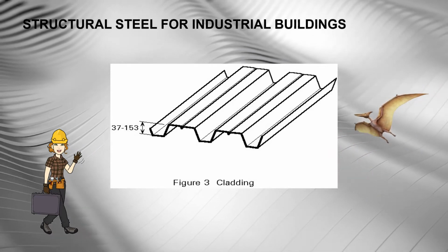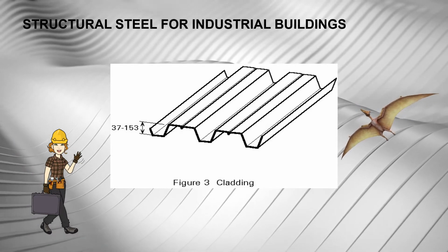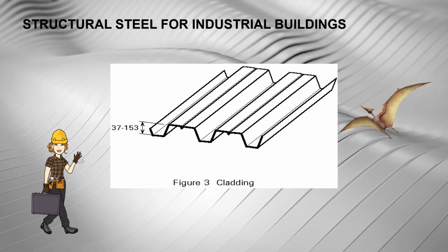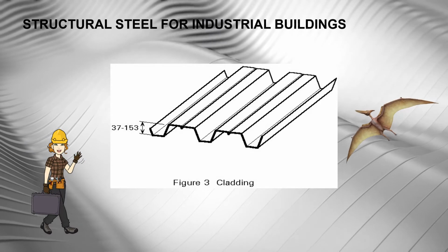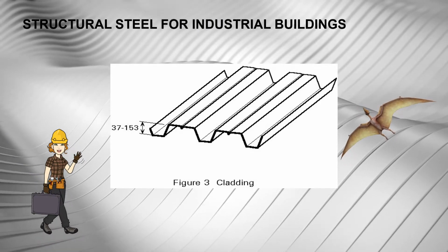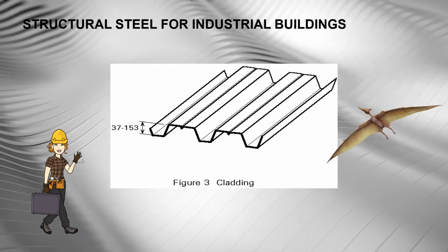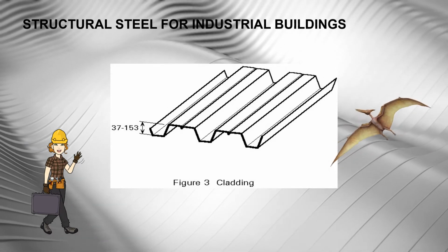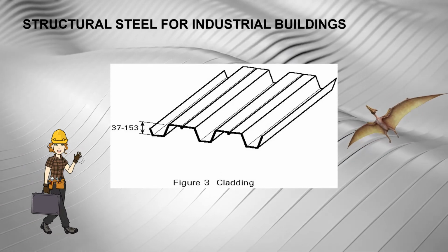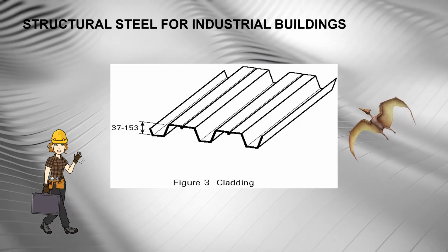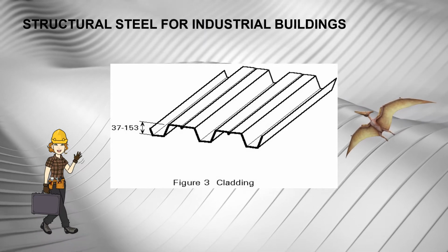Not only is steel a versatile material for the structure of a building, but a wide variety of cladding has been devised utilizing the strength developed by folding thin sheets into profile form, as shown in Figure 3. Insulated cladding systems with special coatings are now widely used for roofing and sidewall cladding. They have good appearance and durability and are capable of being speedily fixed into position.